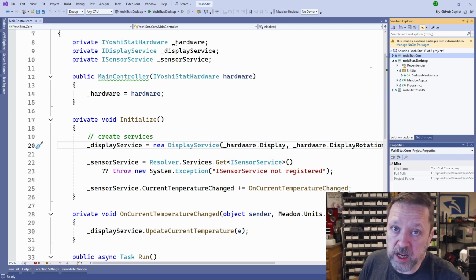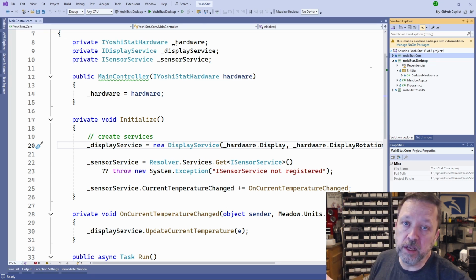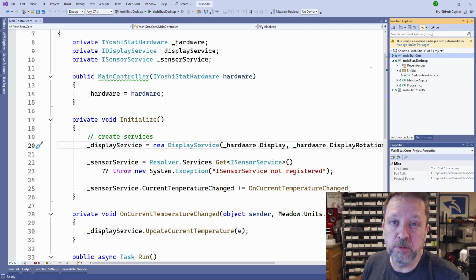But for forced air, which is what I've got here at my house, and that's what I'm going to be designing this for, basically when it says call for heat, call for cool, or in fact call for fan, it just connects and sends 24 volts. 24 volts already comes up to the thermostat, so all we need is a relay to connect those two. So we're going to drive the relays.